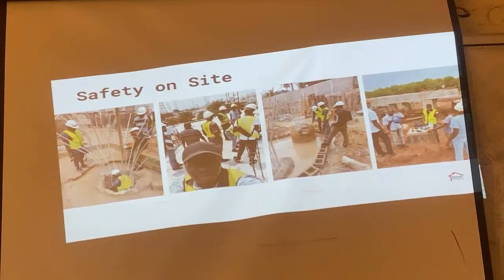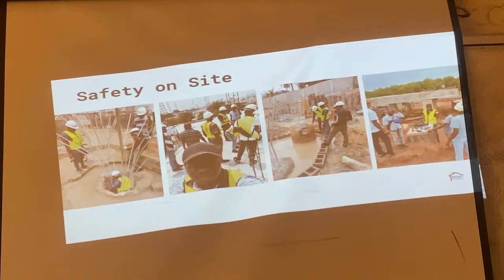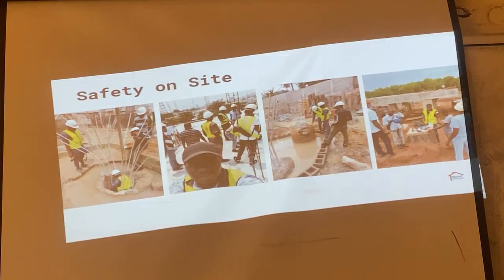We're carrying out a test on a pile. Not which method? Oh, the non-destructive one. I'm sure you know there are pile load tests. This is not a pile load test. This is a pile integrity test. There's a static and there's a dynamic pile load test, but we are not loading the pile. Instead, I want to check for homogeneity of that pile.